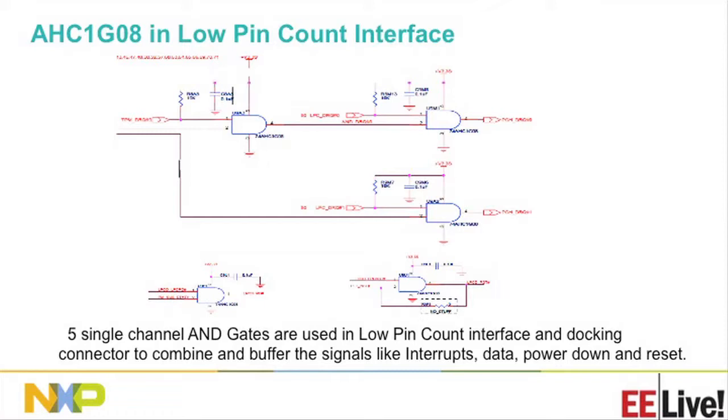In the tablet PCs or so, you will see the AND gates being used to extend the low pin count interface at the docking side. And it also combines and buffers the signals like interrupts, data, power down, and reset lines to improve the signal integrity and signal quality on the board.